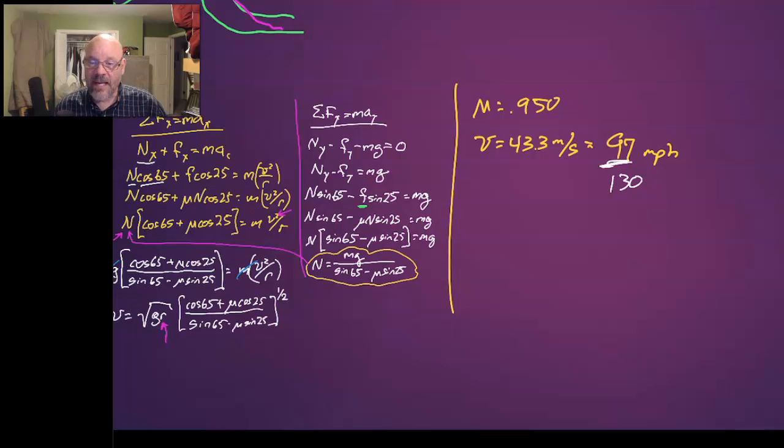All right. Well, then I found out that the tires that they use on the NASCAR cars are very soft rubber, very soft, and they get hot. And when they get hot, they get sticky. Okay. And so it's actually maybe more realistic that mu may be as high as 1.3, okay, because the tires are actually sticky.